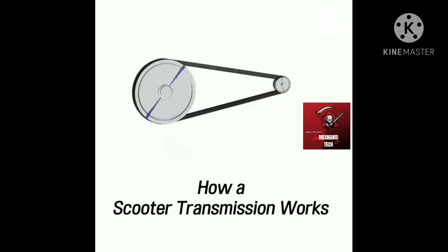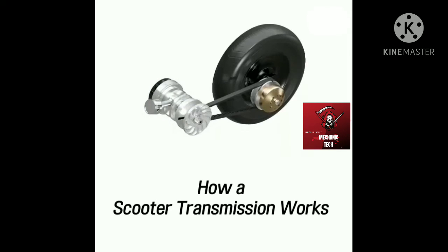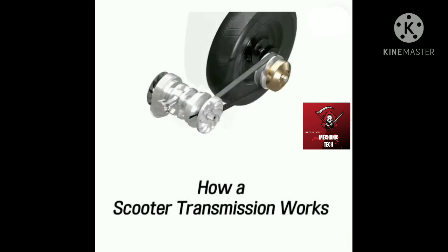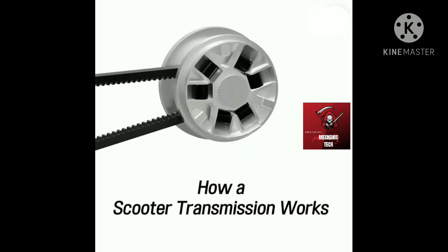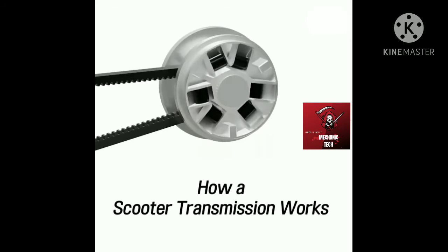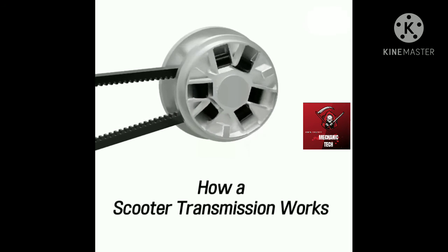To obtain high RPM, the diameter of the driver pulley increases and that of the driven pulley decreases. Let's understand how this is achieved in the actual CVT. The sliding conical plate of the driver pulley has a set of rollers or sliders as shown here. When the engine is at low RPM, the rollers are held near the center of the pulley.